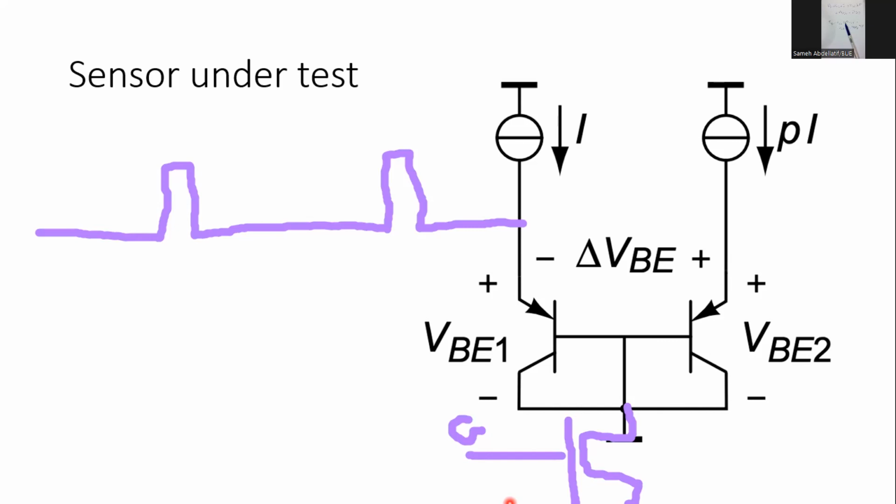We have what's called an off current, which represents some very small current to be consumed even if the signal reaching the gate of a transistor is below the threshold, or what we call the sub-threshold region. That means that, physically speaking, in this region, you still have some power dissipation.